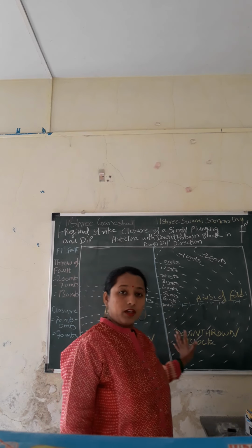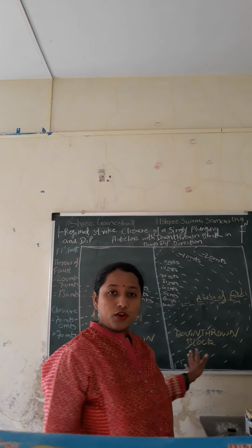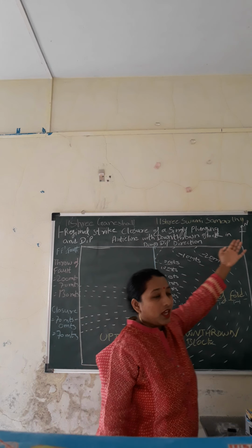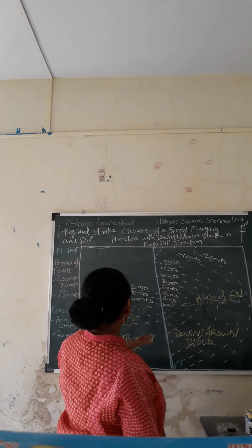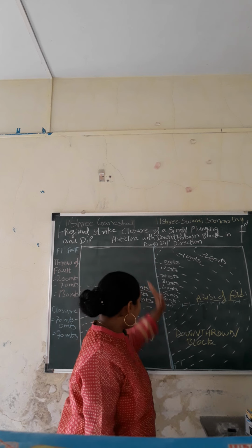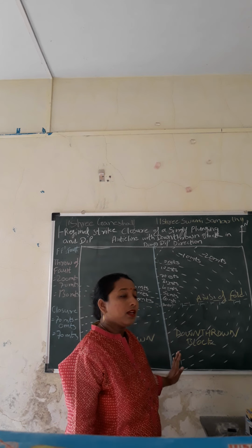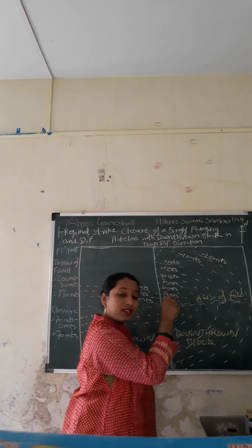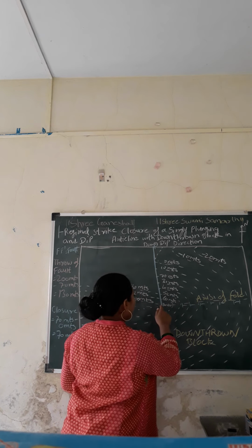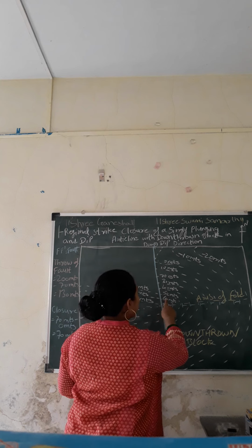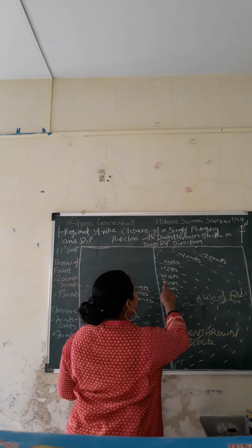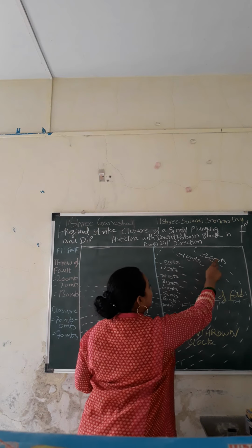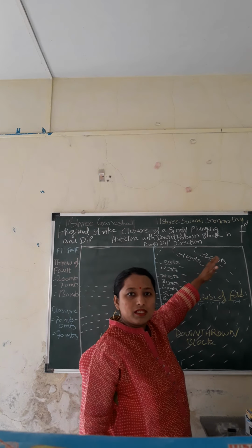Yes, the figure of the contour map has already been drawn here, wherein we get to see the regional strike and dip. We have north marked, and this F and F dash is the fault plane, and we have contours, this being 70 at the crest of the plunging anticline. We have 60 meters, 50 meters, 40 meters, 30 meters, 20 meters, 10 meters and 0 meters, and then you have minus 10 and minus 20 meters, that is below the mean sea level.